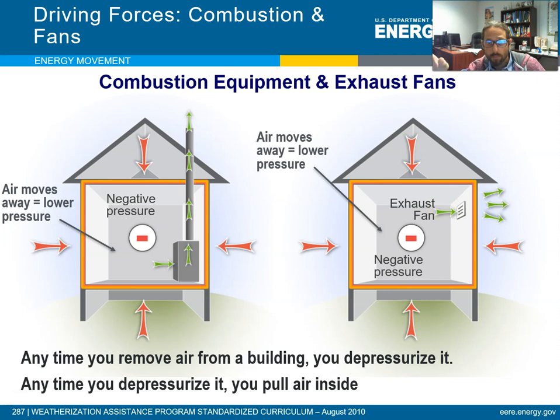For every cubic foot per minute that goes out of the building, it's actually drawing in another cubic foot per minute. It's drawing air in through the depressurization that's happening. Okay, so again, air moves because of pressure differences. That's it. That's the whole game. So if you're moving air, you're causing a pressure difference, which then makes more air move.